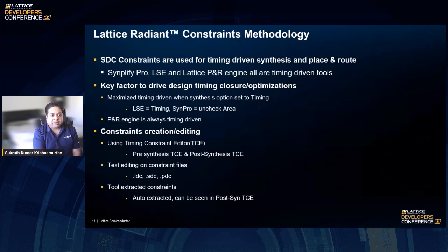Some of the key factors to consider to drive design timing closure include maximizing timing-driven synthesis when the option is set to timing. If users are using LSE, always make sure the strategy option is set to timing. If you're using Synplify Pro, make sure that you uncheck the area in the strategy options. Our place and route engine is always timing driven.